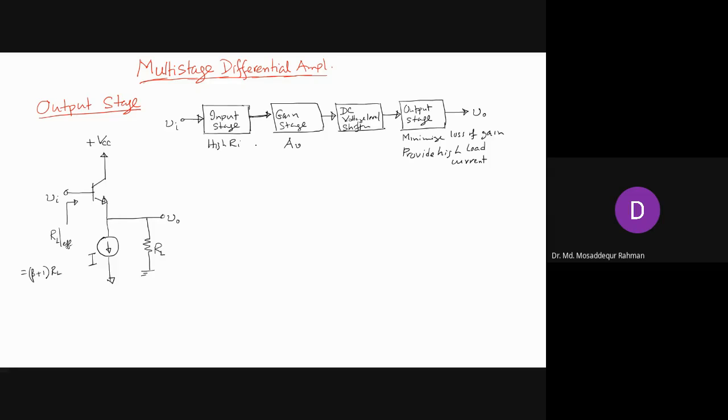And also we said that at different stages, when you design the amplifier circuit, you have to ensure that all the transistors are properly biased. And biasing means both the collector current and collector voltage are high enough to support your signal voltage and current, which is also known as the operating point, right?